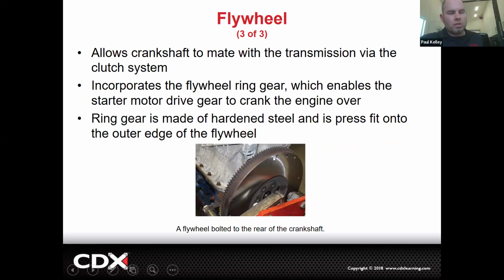This was a flywheel that was machined. So let's say you're going to do a clutch disc, a whole clutch service. You could get a new flywheel, or you could send that flywheel to the machine shop. And the machine shop will actually, they don't necessarily turn them on a lathe. We did turn one on the lathe once as an experiment, but they'll use a different type of flywheel surfacing machine. It's more similar to how they do a cylinder head. It's kind of like a grinder cutter. So that one would be freshly redone.